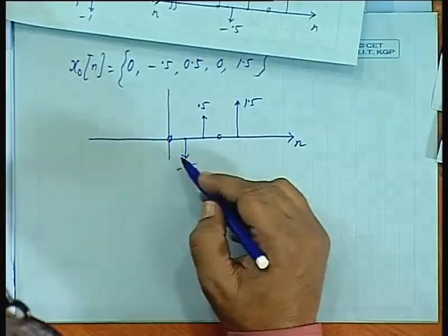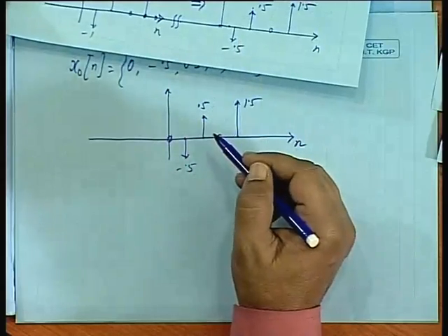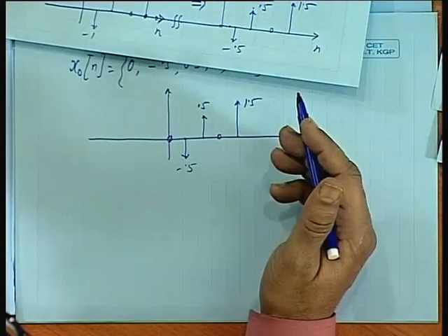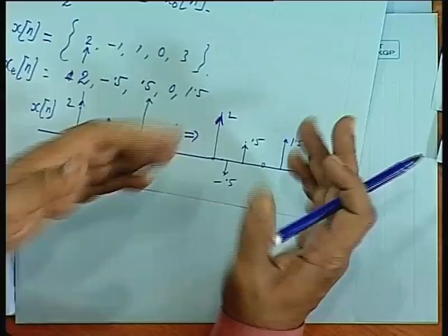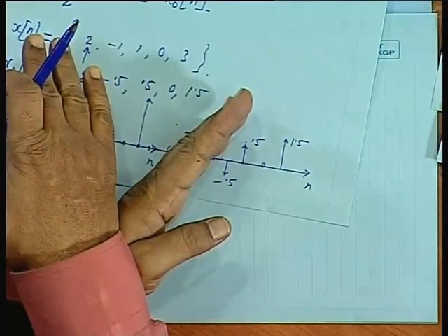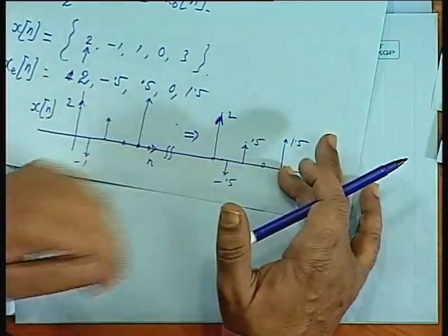So you mean to say except the first value, an even function and odd function will appear identical? So where is the difference? Even function: though we are showing it only in the positive region of time, it also has its counterpart in the negative region which has not been shown. So the total function is a mirror image of this plus this itself. If you take a mirror image on this side and then club with this, that will be the even part x e n.